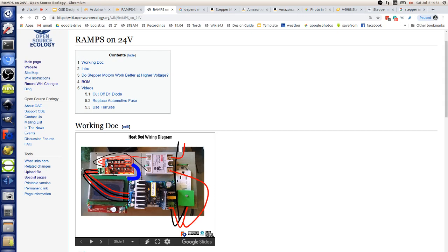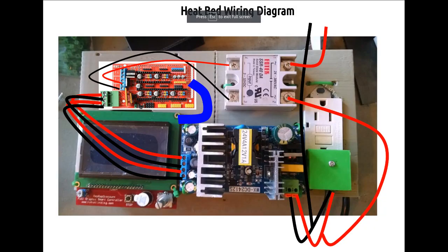No, there is. I'm sorry, there is. The one thing that does use the 12 volts is the signal to the relay. The hotbed is activated by 12 volts, which activates the solid state relay to the 120 AC heat bed. So yes, we do need that second connection. We're using the upper connection, which is 12 volts, to feed the heat bed turn on, and we also use it for our little voltage step down. I mentioned that we cannot power the Arduino ramp system from 12 volts because it blows the voltage regulator, because we have the LCD and so many components on top.